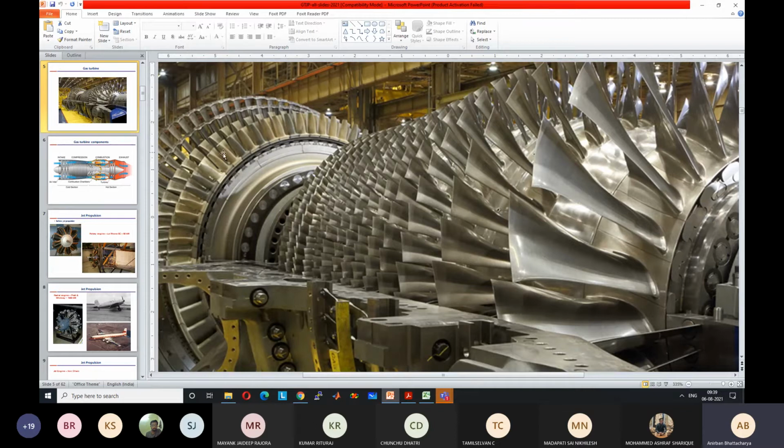So the turbine blades can have this kind of very twisted profile, because there won't be any flow separation because the flow occurs along the pressure gradient. But if you had put similar profiles here, there would have been flow separation and caused dramatic reduction in the efficiency of the compressor. As a result, you cannot have very much twisted blades. As a result, the pressure ratio is much lower.